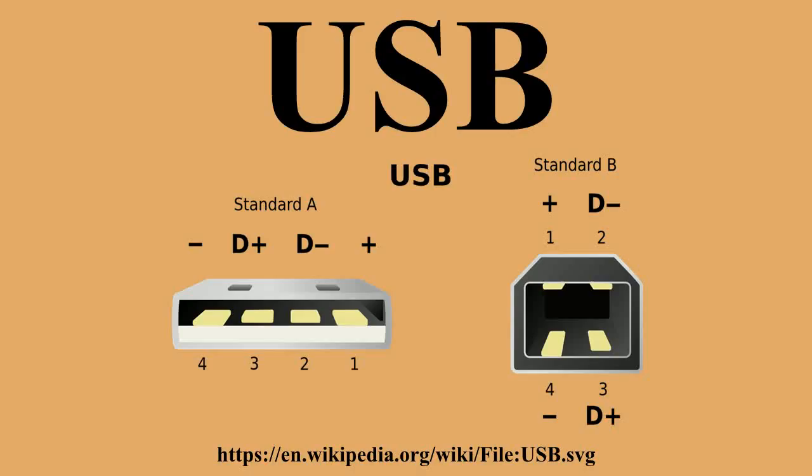The host controller directs traffic flow to devices, so no USB device can transfer any data on the bus without an explicit request from the host controller. In USB 2.0, the host controller polls the bus for traffic, usually in a round-robin fashion. The throughput of each USB port is determined by the slower speed of either the USB port or the USB device connected to the port.